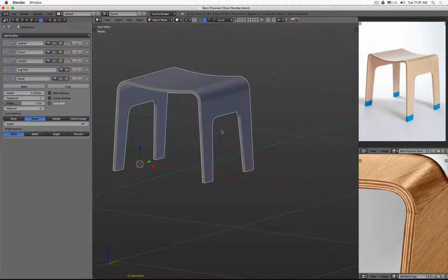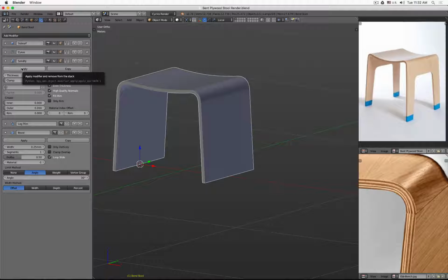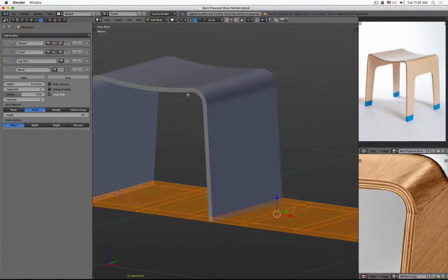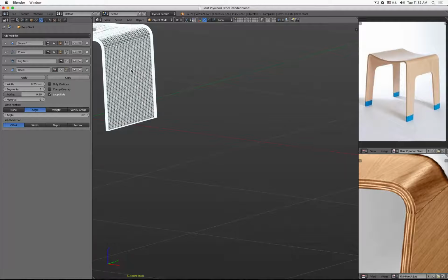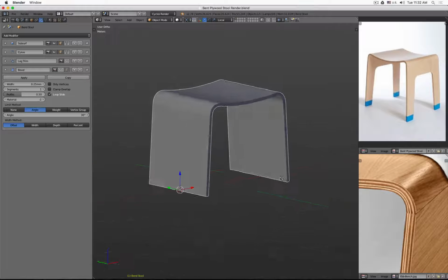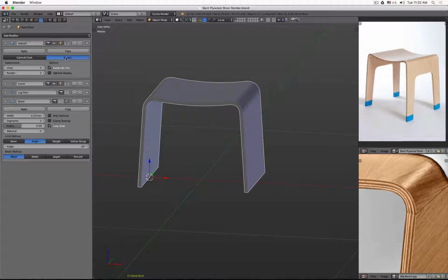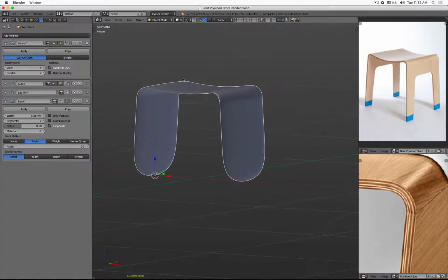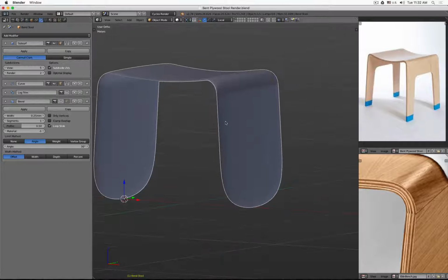So what we have to do in this case is actually apply the solidify modifier. So I will turn off, for example, the boolean modifier and the bevel, and then the solidify modifier I just have to apply. So for the render model, that's just normal. Click apply, and then there is our part. This actually remains nice and straight, also because the subdivision uses simple and not Catmull-Clark. If I use this one, you see then it's round. If we use Catmull-Clark, not a big deal.